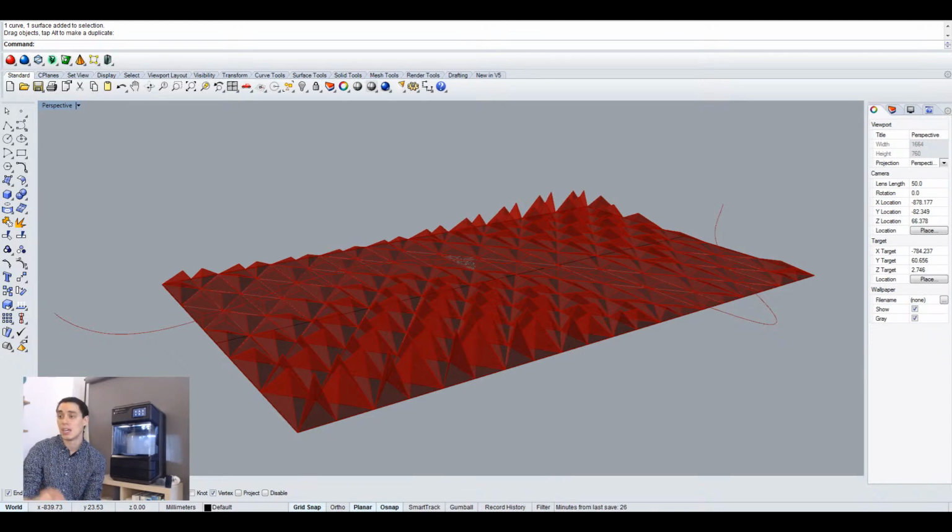I'll give you an example. What you're seeing right here on my screen is, I'm taking a surface. Let me hide all of this. But I'm taking that surface and that curve, and I'm asking the model, first, to split that surface in a number of panels, right? So you see those triangles that are being created. I want to use 20 by 10, or let's say 10 by 10, and you see how that adjusts my model automatically.